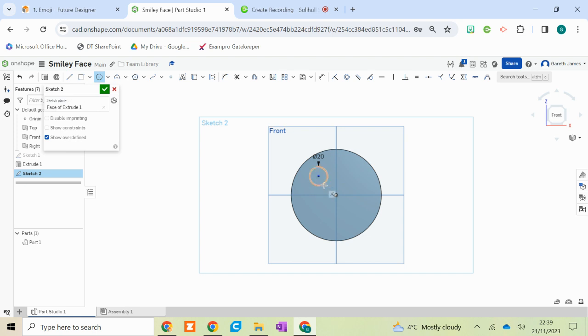And what you'll now notice is as I move to the center of this first circle, I'll move across carefully. I now have a dotted orange line, which gives us a reference point. So on this second circle for the second eye is in line. I'll purposely make it the wrong size, but again, I'll just type in 20 and I'll hit enter.